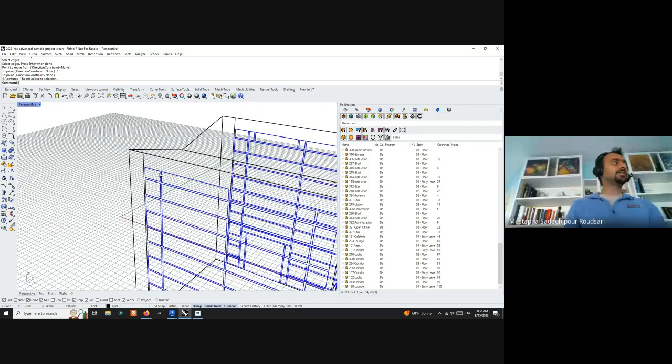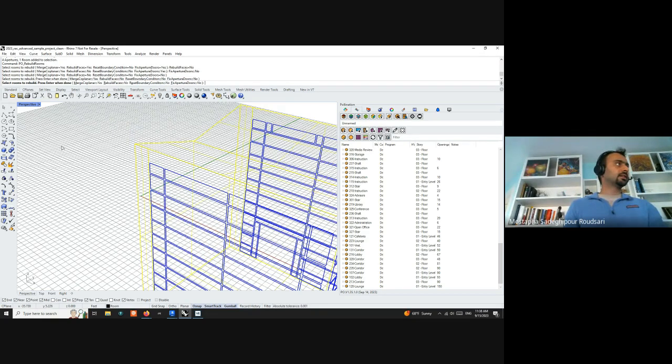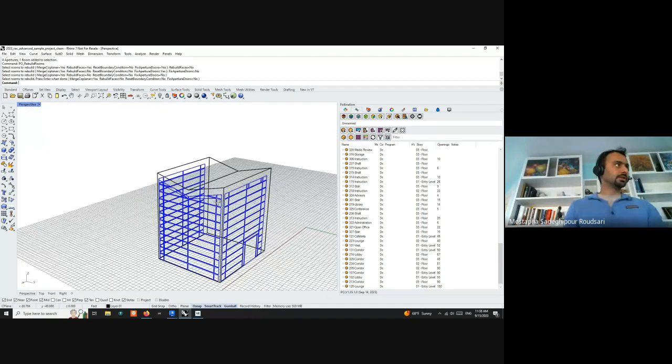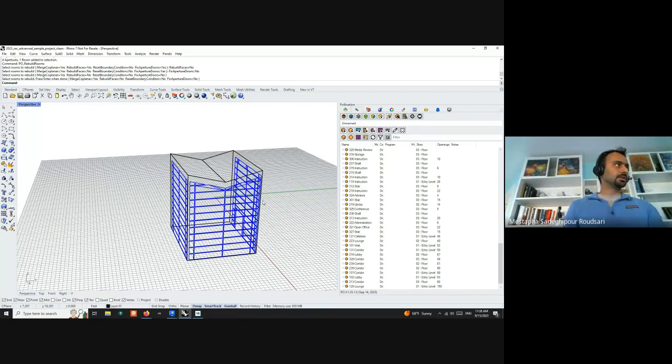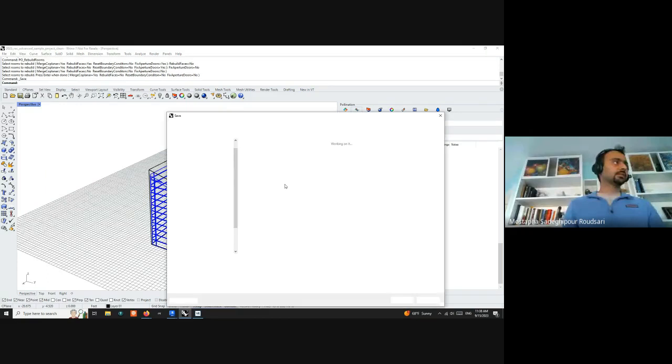You see this one is chopped because this one was exported from Revit, and there are two different walls. So this is the command that I mentioned: you can do PO rebuild rooms, and then set merge coplanar faces to yes. You don't need this for now. For boundary condition, I don't need it. Fixed door windows, I don't need that. So I just select this, and this basically resolves it. Any coplanar faces that are split will be merged using this simple command. So that's one thing that I wanted to do. That's a good time to save the file.